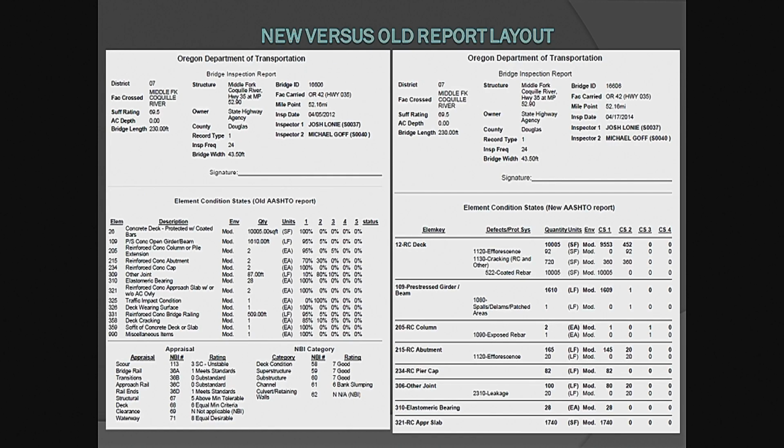If you're talking about your decks, they are going to be on a square foot. So then they go through and, for ease of computation when you're in the field, we just assume that a crack's going to be a foot wide for our computation, and then they'll measure the length. So if you had a crack, say a 1/8 inch crack, and it was 5 feet long, we would say that would be 5 square feet of cracking.